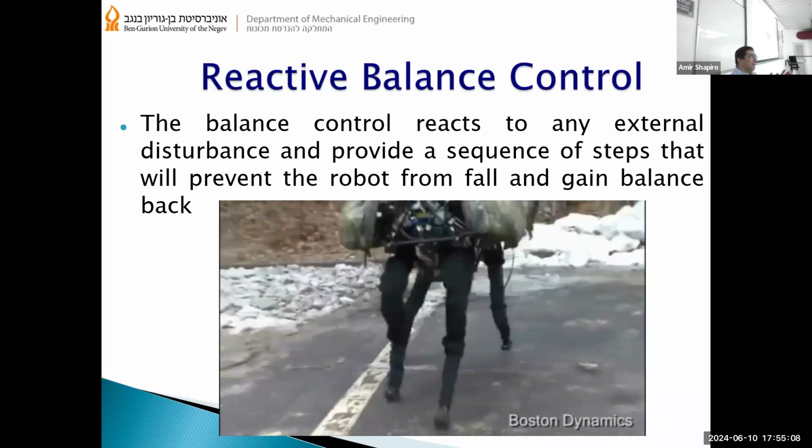They are relatively big to provide high torque at low speed. With direct drive you can also sense the environment, sense the current, the back EMF, and then identify how much torque the motor applies.